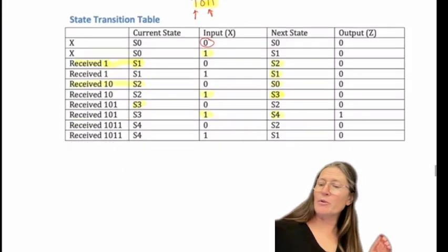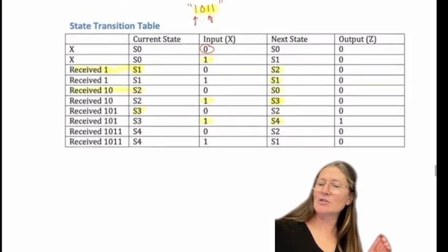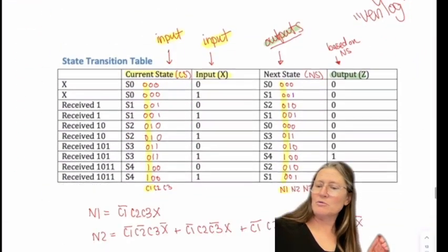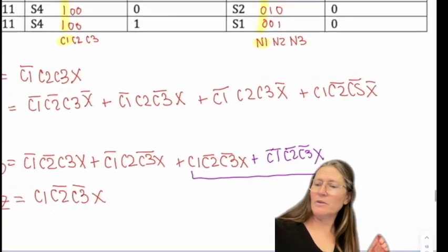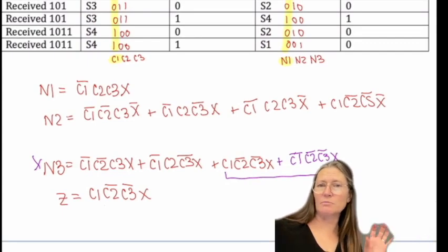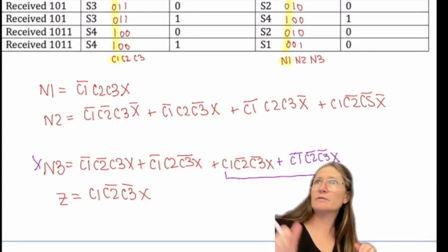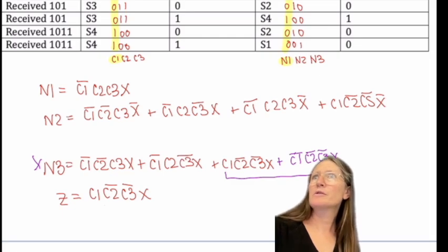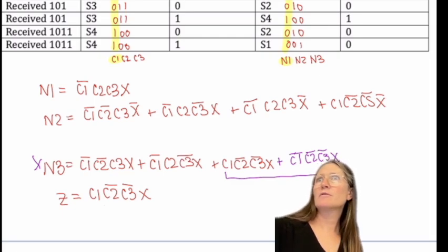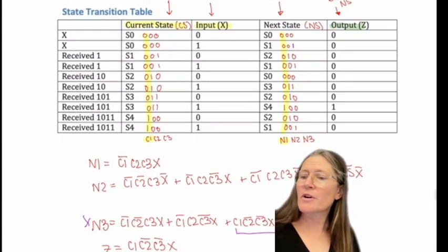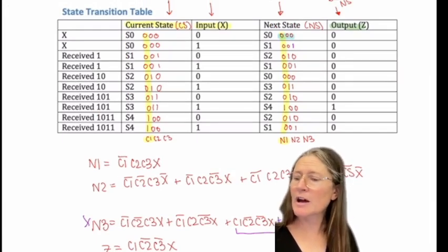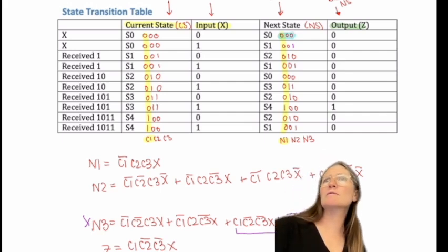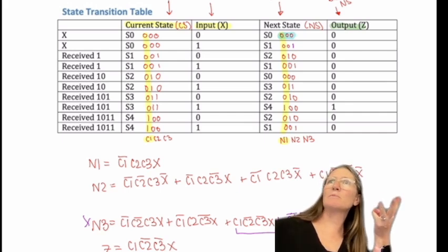I could give you a table like this and ask you to derive the Boolean expressions, or the actual digital logic for each of those. Yes. So depending on how many states there are, you need the number of states minus 1 flip-flops? In this case, I have 3 digits to define those states, so I need 3 flip-flops in there. Yeah.